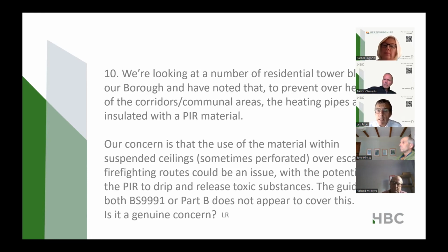And under those circumstances, I wouldn't see any reason why you shouldn't remove that PIR and replace it with a mineral wool because of other non-compliances. The thing is with fire safety, certain aspects are allowed to fail, but if you haven't got full compliance to begin with because you're dealing with an existing building, then whatever you can do to minimize the risks, you would do it. And if the people at the London Borough consider it an issue, then they should replace that PIR with a mineral wool heat lagging that's covered with an aluminium foil. Okay, make sense?